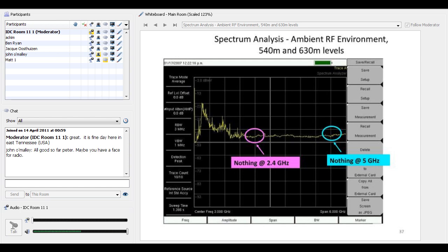So I was underground with a radio frequency spectrum analyzer, 2007, doing these measurements. And there are specific frequency bands. 2.4 gigahertz is the one around the world. So a vendor can sell their products in the UK, Tanzania, South Africa, Australia, US, Canada, and they can all work at 2.4 gigahertz. The other places around the world have different frequencies that you can and cannot use. In Canada, they could use 5 gigahertz. Underground, you sort of can use anything you want, but if we're all stuck in an open pit or on a mountaintop, you have to live with the local jurisdiction.